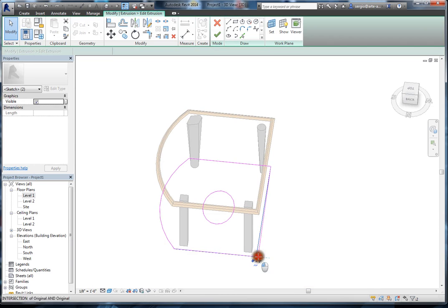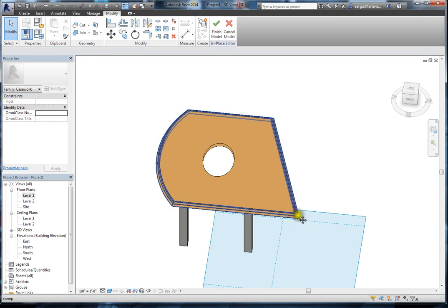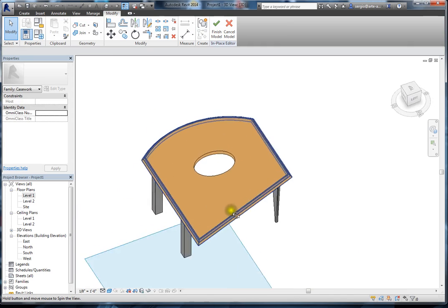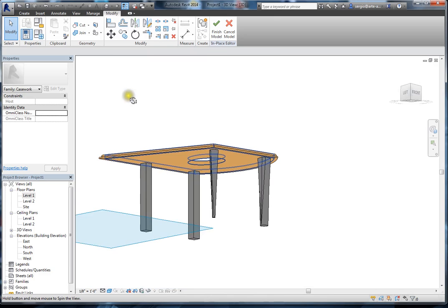And what I'm going to do is I'm going to just change the shape. And I hit OK. Notice that the sweep goes with it. So even after the sweep is created, and you go back and change the original shape that the sweep is attached to, the sweep will automatically update to whatever shape you created afterwards. So that's kind of cool.